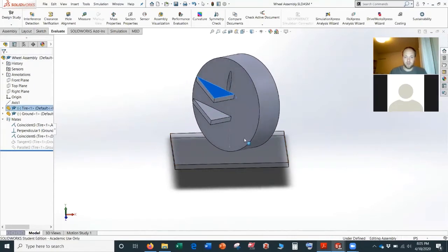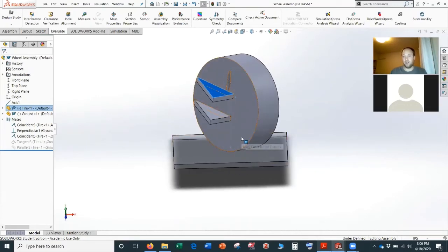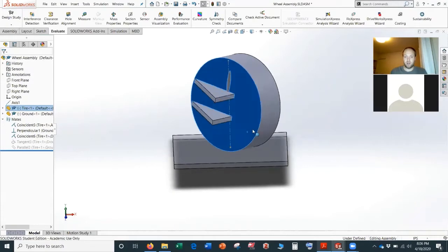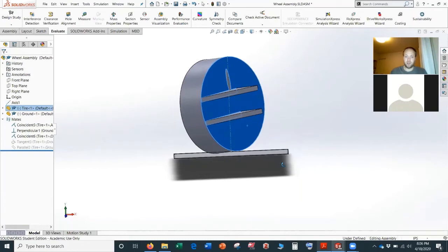So you'll notice that this is intended, in the rest of the demos, to be the front side, and this will be the back side right here. So the tire's traveling over on the right side. If we look down now, you'll see that when you have some kingpin inclination, your tire will subtly start to go into the ground when you go forward. Let's see what happens. From this, the front left wheel, that's making a right-hand turn, and to make a left-hand turn, it also goes into the ground.